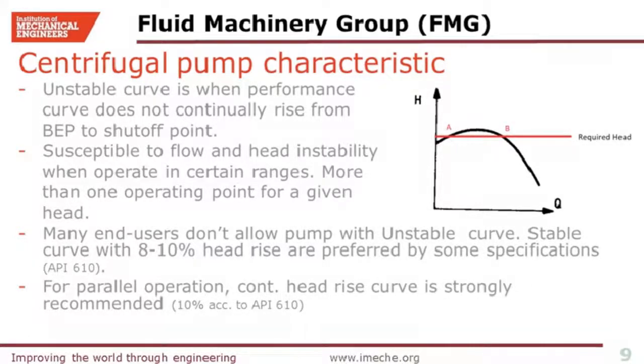Having said that, it doesn't mean that pumps with unstable curve should be ignored. In fact, pumps with unstable curve generally have higher efficiency than other pumps. As long as you tune your pump and system carefully, unstable pumps can be used.